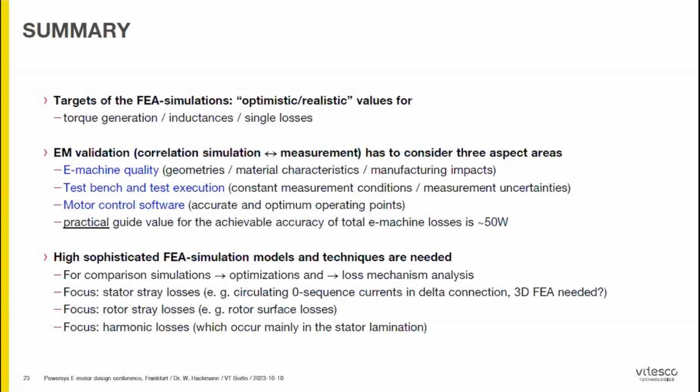But the highly sophisticated finite element simulations we need, and we need also the techniques. We need this for optimization, and we need this for analysis. So as I said before, we are discussing here the harmonic losses, and the harmonic losses are a big point for WLTP energy efficiency.